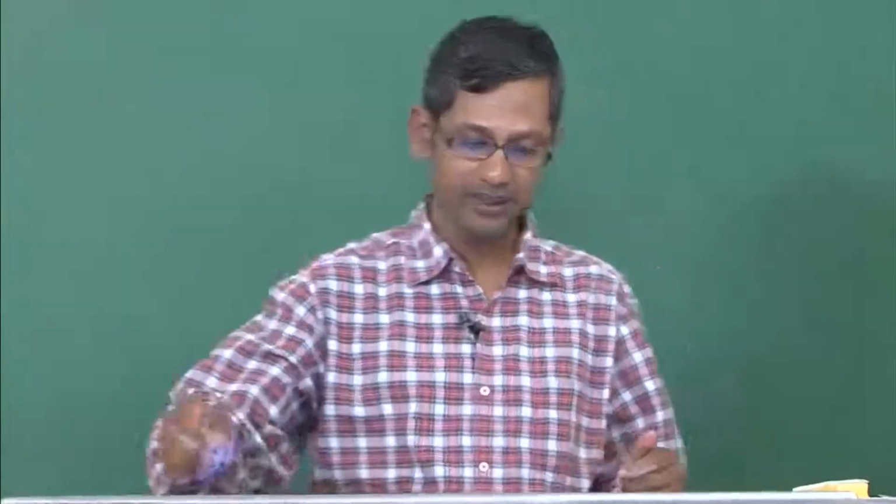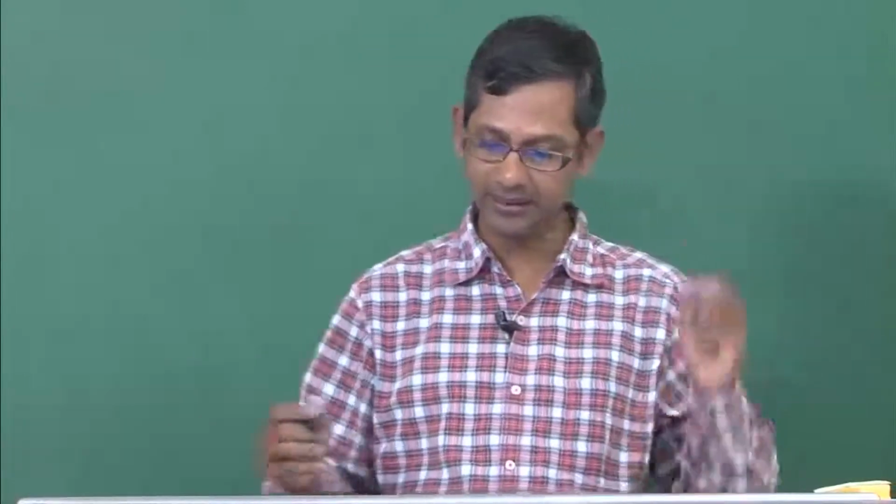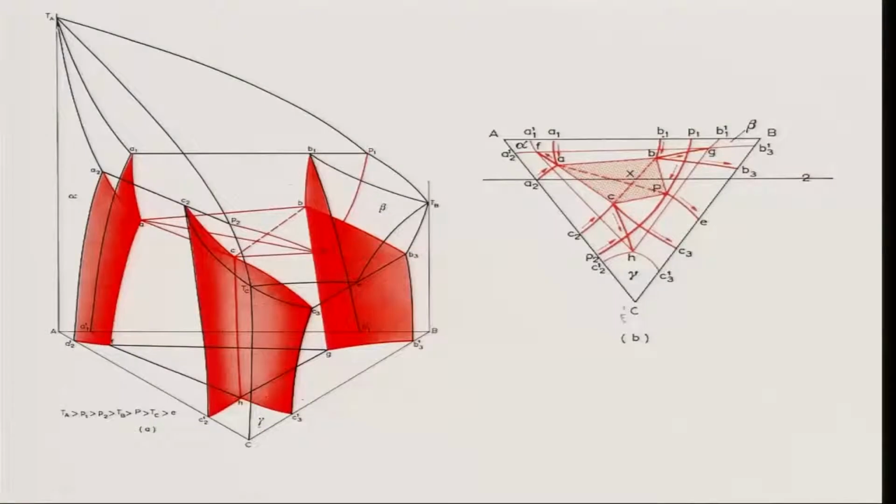I am going to show you another case. Okay, actually the same thing, so that you can understand in a better way. So, see if you look at that A, B, C, right, A and B, A forms a peritectic, and this peritectic is represented by P1, and AC forms a peritectic that is represented by P2. You can clearly see this is a peritectic. On the other hand, BC forms a eutectic which is represented by E. Now, these points which I have drawn inside A, B, C and P, correct.